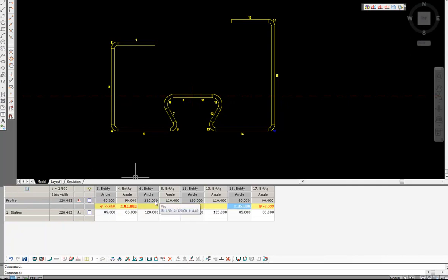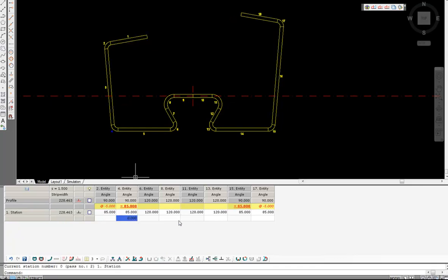Okay, let us now try using the new bend sequence. Previously this was only possible by using interactive unfolding in the old COPRA interface. So, let us pick a position where to unfold. Well, first of all, this will be Entity 4 and Entity 15.